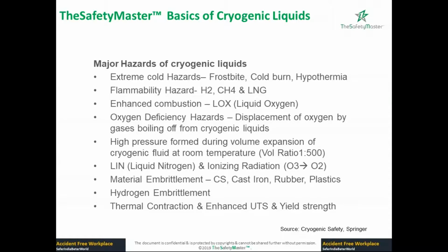Or if you're wearing clothing and you are exposed to an oxygen atmosphere, the clothing will absorb oxygen and you come out of that zone, but the oxygen is still inside your clothing. So if you go outside the factory and light a cigarette, immediately your clothing will catch fire. That's the problem with oxygen.